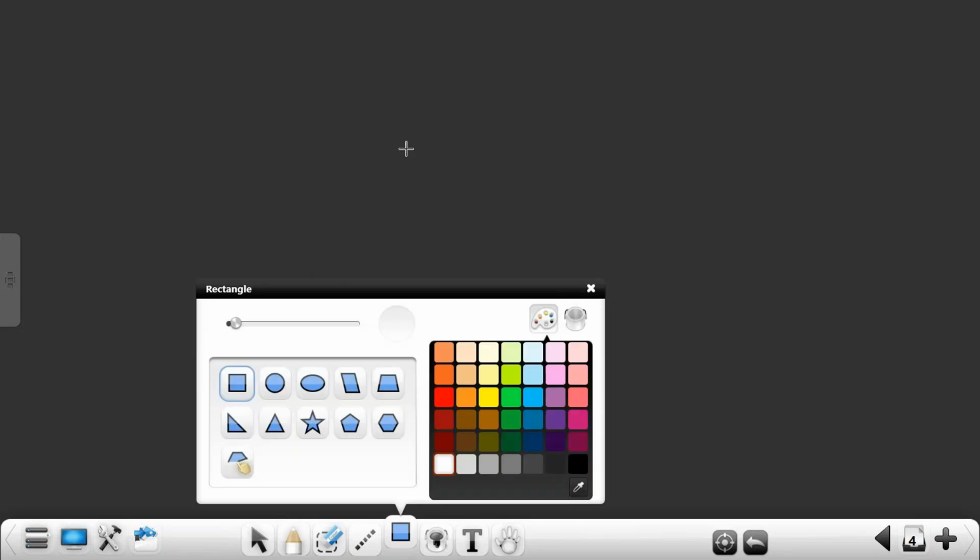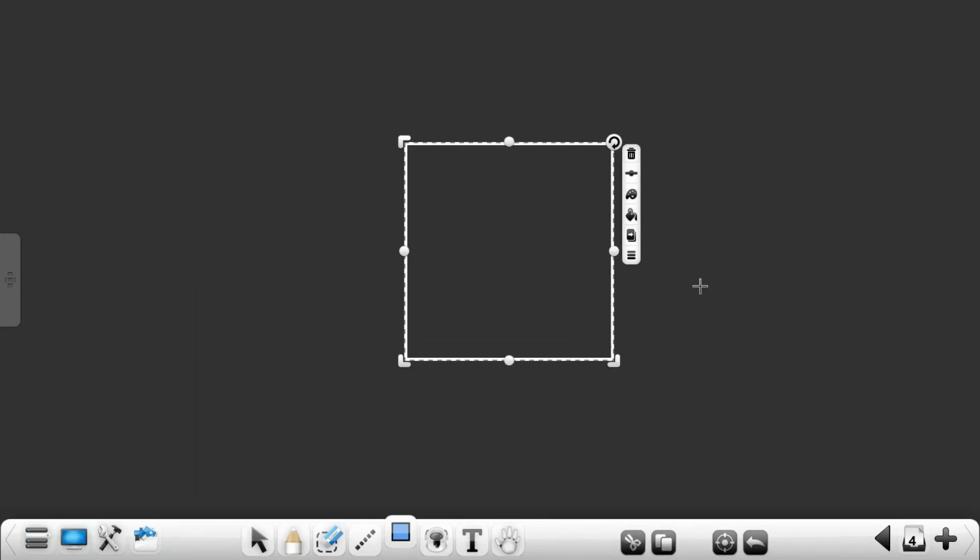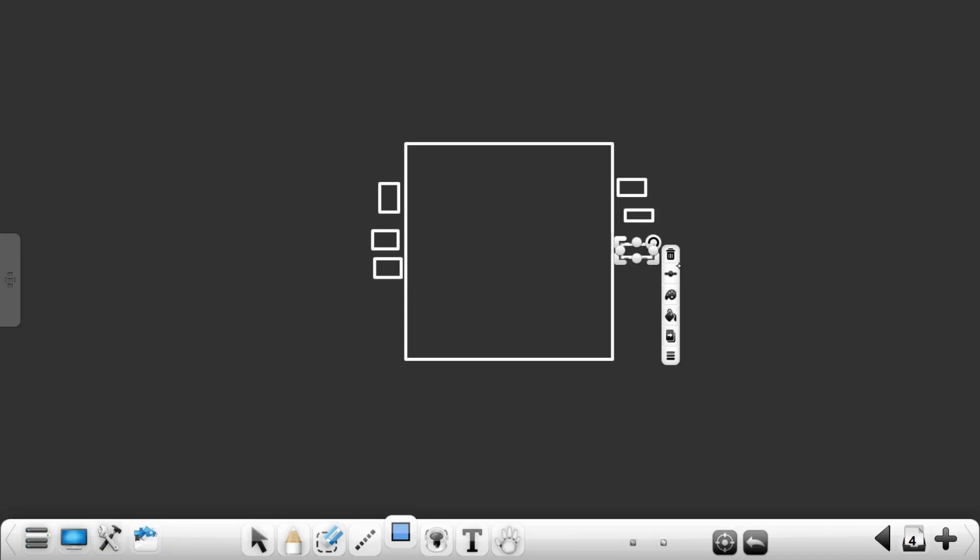So okay, the IC comes out. How do you test? If this IC is for mobile phone operation, would you incorporate this IC in a mobile phone and test it? No. How do you test? For testing, you will have some test in port and some test out port. You will apply some vectors at the test port. Vectors means bits.